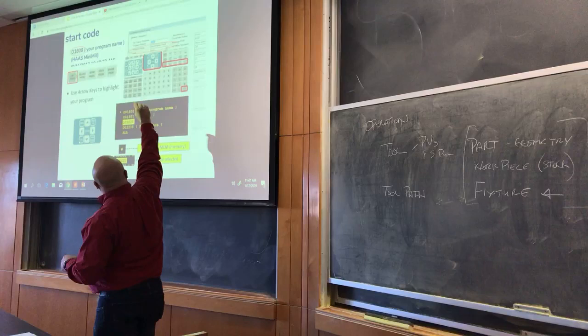Does Esprit put that in by default? If you choose the mini mill post processor, it goes in by default because in the code that defines the post processor, we hard coded that in. So all CAM software, Esprit, Fusion, the SolidWorks thing, whatever CAM software you're using, it has a tool that goes from what the CAM software understands to what the machine understands. That's called the post processor. In Esprit, we can freely edit that, and we can make those kind of changes, which is one of the reasons we use Esprit.